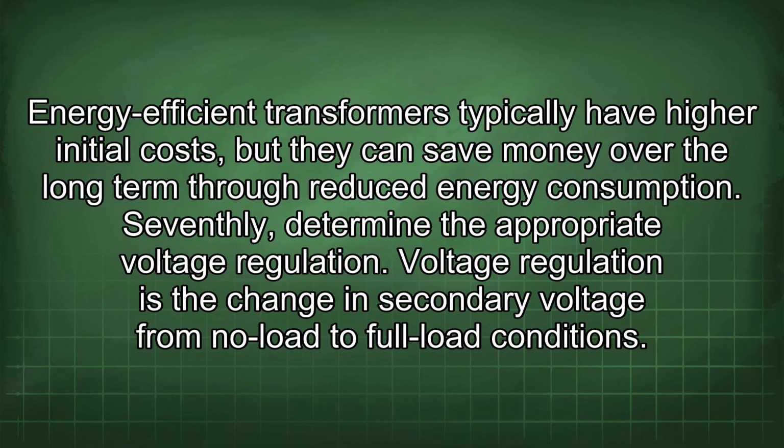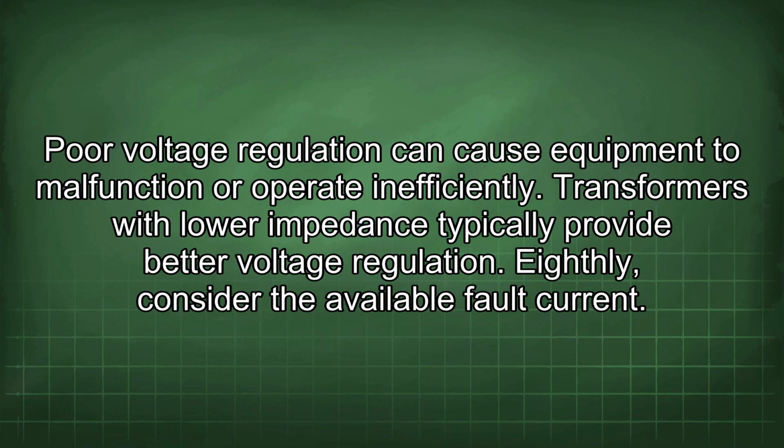Seventhly, determine the appropriate voltage regulation. Voltage regulation is the change in secondary voltage from no load to full load conditions. Poor voltage regulation can cause equipment to malfunction or operate inefficiently. Transformers with lower impedance typically provide better voltage regulation.